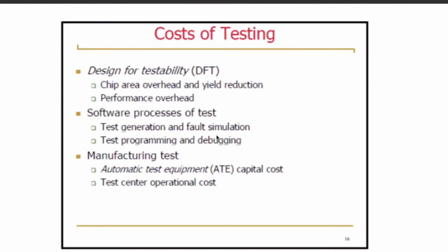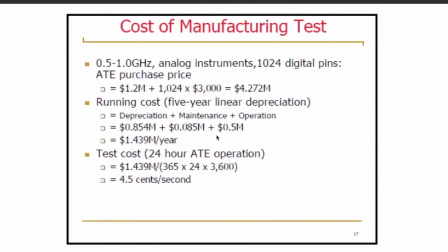After fabricating, they will use the ATE machine, and the same result of the test generation process you have done in the test development phase will be applied to the ATE machine with physical chips, and then we will see the real manufacturing test. So here we have defined the cost of the ATE machine, justifying our statement of how huge the cost of testing is.